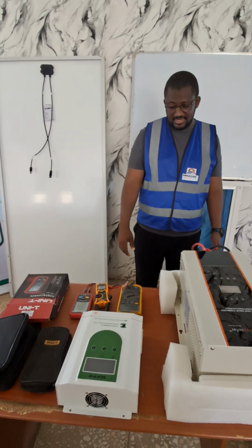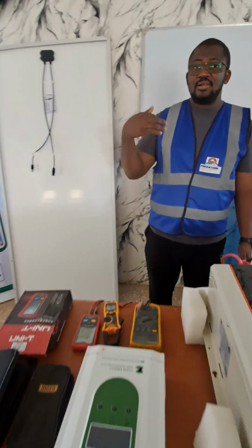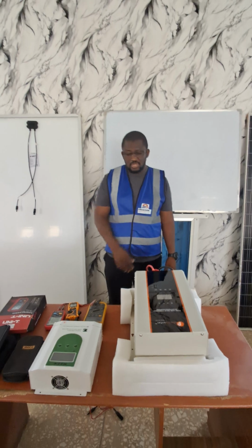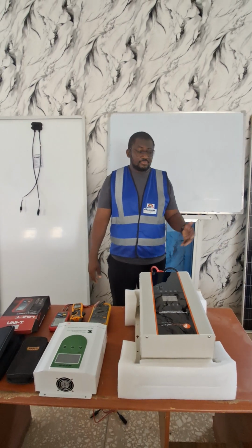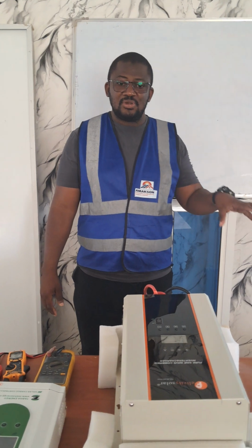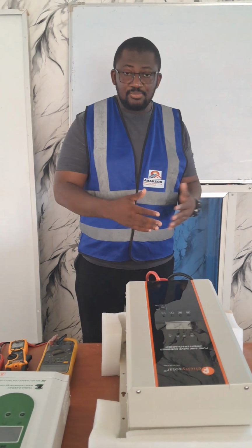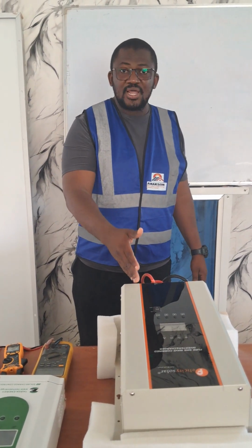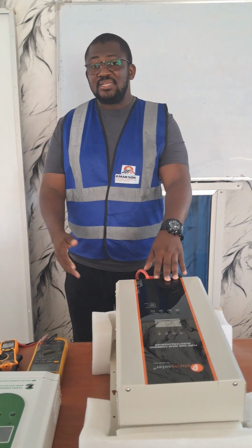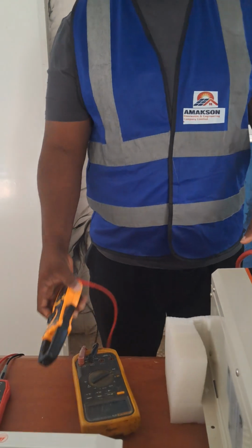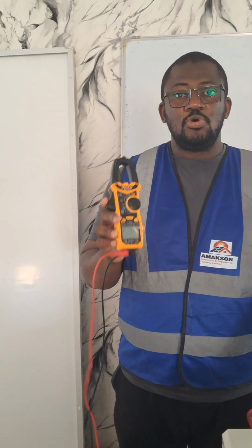said solar system applications, starting from solar panel, its parameters, the open circuit voltage, short circuit current, maximum power current, and what have you. For the battery, the voltage is the rated voltage of the particular battery, and for the inverter, the open circuit voltage, the system voltage, and then input and output voltages. We obtain them through our multimeter, and then we measure current, whether it is AC or DC current, through what we call clamp meter.